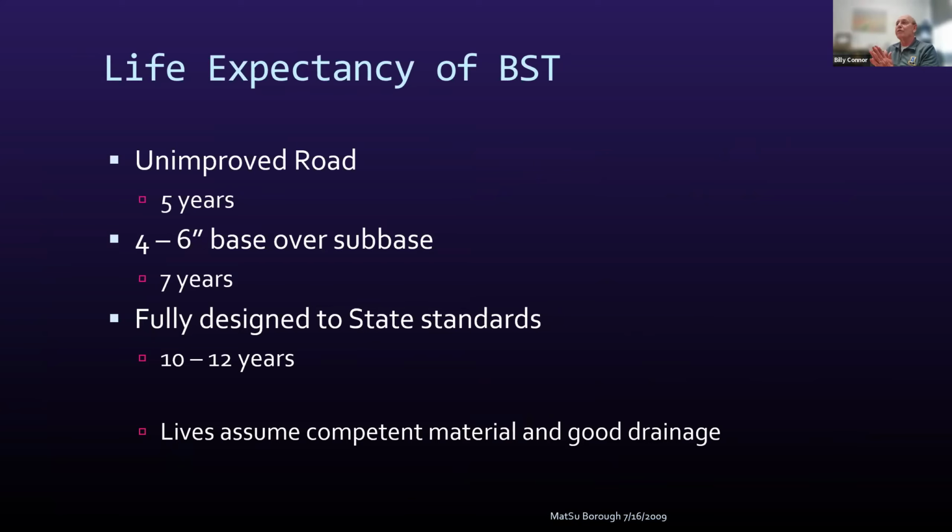As I said, the life expectancy is about 5 to 7 years. We can double that with the use of fog seals. Usually, I like to use about 4 to 6 inches of base course over our sub base. That increases the life a little bit, and we have a number of chip seals around that were designed to state standards that have lasted 10 to 12 years or even beyond that. So it does work pretty well. But again, we're assuming that we have good pavement structure and good drainage beneath in those areas.